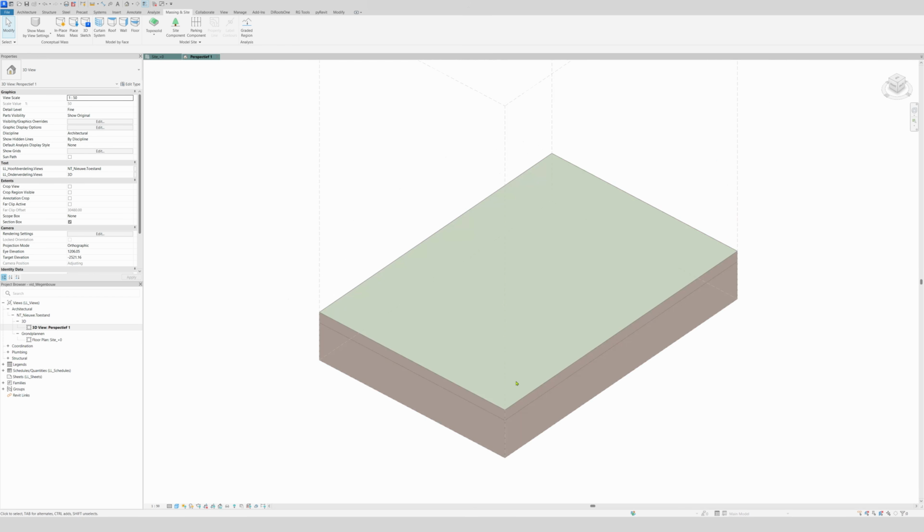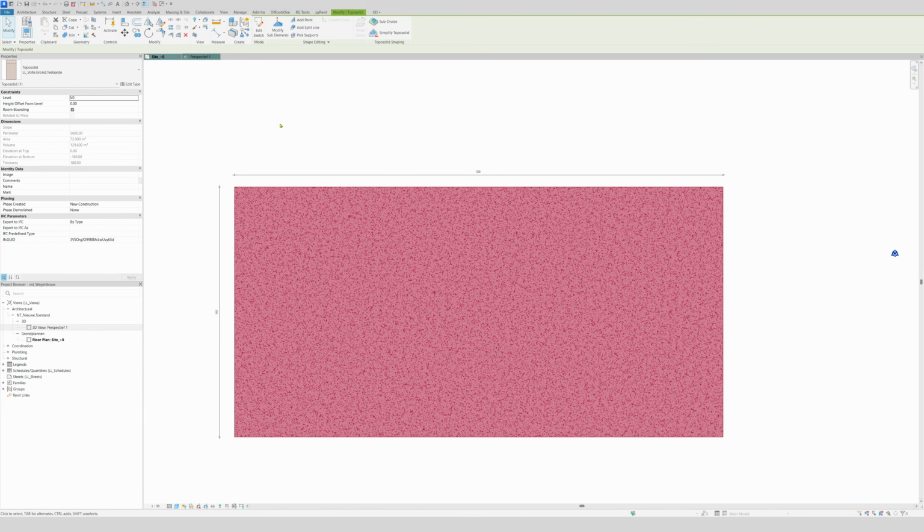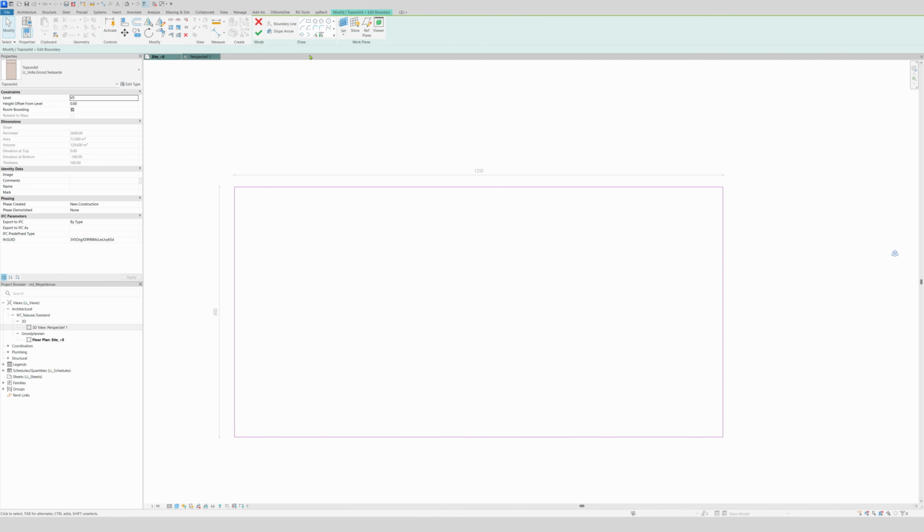Now in 3D we have our base topo solid, just a flat one, and now we're going to create the infiltration basin or pond. By that we're going to make the contours of it first, so we select our topo solid, Edit Sketch, and now we're going to make a nice pond, for example right here, and maybe do something like this.